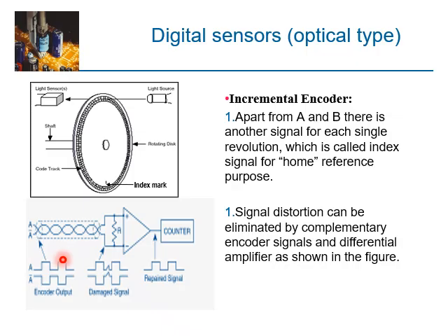So what happens if there is noise in the channel? Let's say you have a nice signal here, as you can see, then there is a certain spike of noise, which is around 3.3 volt. And that noise will cause the controller to detect a false signal, a false count. So it will count an extra pulse as a false count here. To overcome this problem, we use a twisted pair cable for each channel, so that we make sure the amount of noise is exactly the same on both channels.